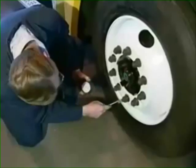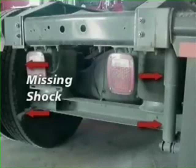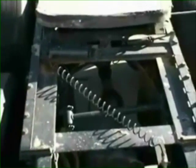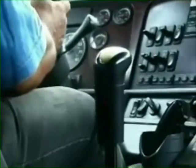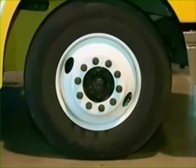If so, check to see if the tire inflation is too high, or if the suspension is worn or out of tolerance. Is the airbag height set too low? If the vibration occurs during braking, then check for cracked brake drums. If the vibration occurs when accelerating but not coasting, then it is induced by the drivetrain. However, if it occurs when accelerating and coasting, then check the tire wheel assembly.